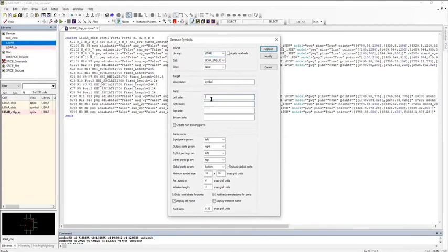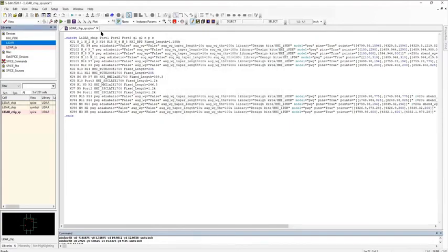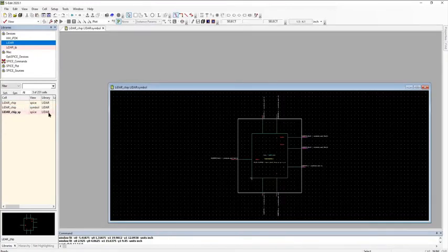For example, let's say we want 2 ports on the left side. We would write port 1, port 2 here. These port names need to match the port names that are defined in the subcircuit. We have already one defined here, so I'm not going to go through it, but I'll show you the resulting symbol. Here's the resulting symbol. Finally, you can use this in your test bench.